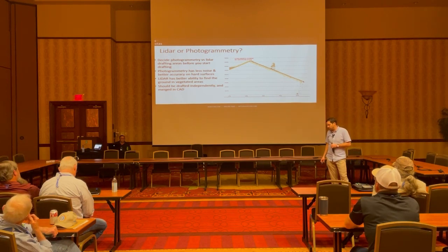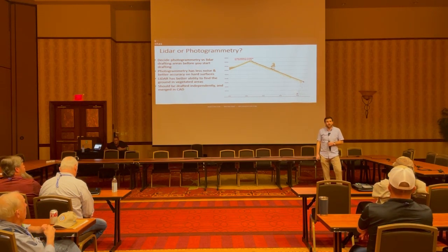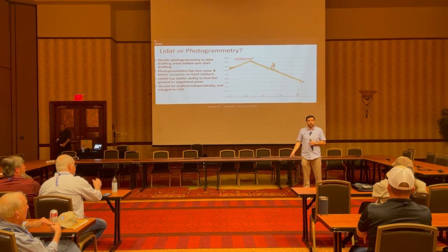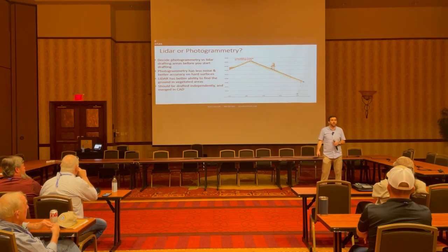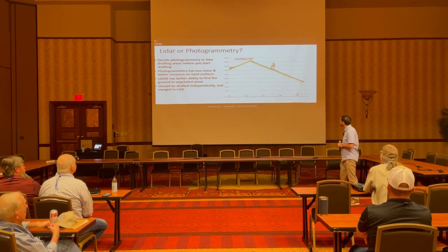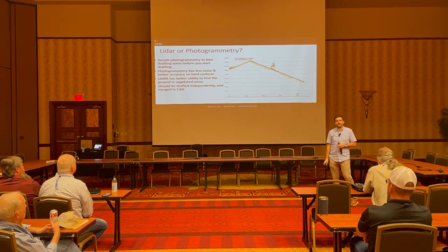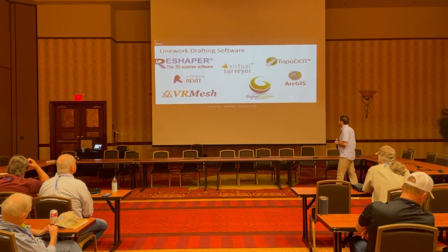Because there are other things, I mean, even with, take paint striping, for example, just in a parking lot. If you're doing an ALTA survey and you need your paint striping, pulling that out of a point cloud is actually kind of hard because visualizing, seeing where all the paint stripes are is difficult to do. Mapping that on an ortho photo or drafting that on the ortho photo directly is extremely easy to do, and it's really easy, again, for a human to say, oh, there's a car parked on top of this line, but I can draw the line underneath it. It's really easy there. So blended workflow we think is really, really useful and probably the top tier approach for LiDAR mapping. Is not exclusively LiDAR mapping, but using both.